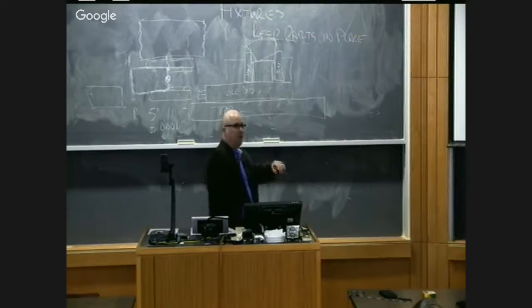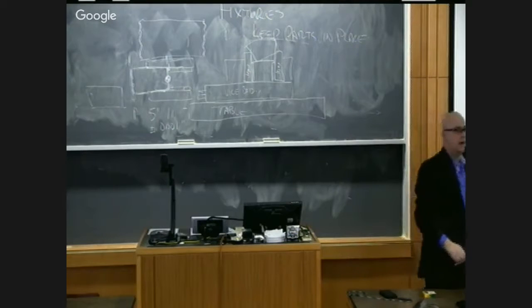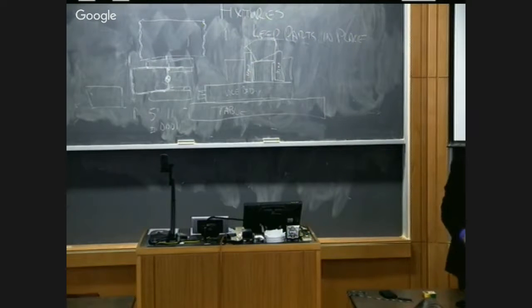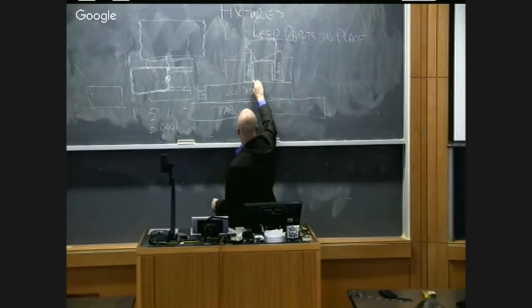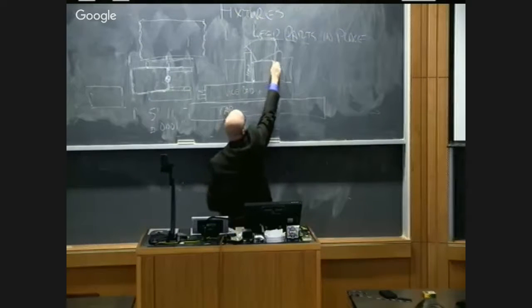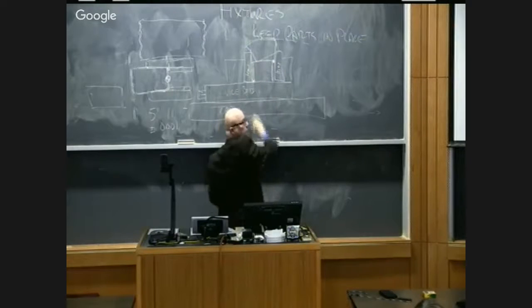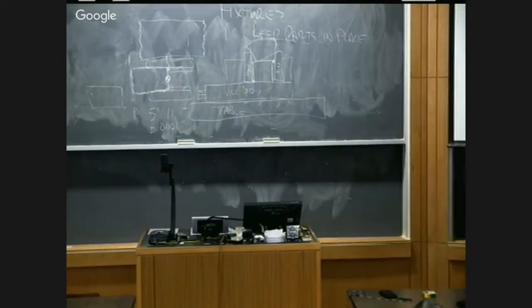So, what are the failure mechanisms using parallels, using a vise like this on the table? How could it become unflat? Because it happens all the time. If there are chips in the way. So if there's chips underneath this one, no chips underneath that one, chips here, no chips here, right? So that will make your part sit unflat. What else could go wrong?